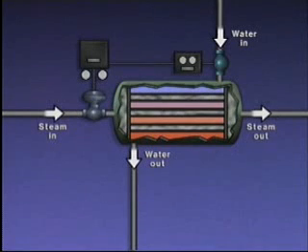For example, the feed-forward control system that we just looked at responds only to changes in the temperature of the water entering the heater. Other disturbances, such as a change in the pressure or temperature of the steam entering the heater, can also affect the outlet water temperature. But those disturbances will go unnoticed by the feed-forward control system.